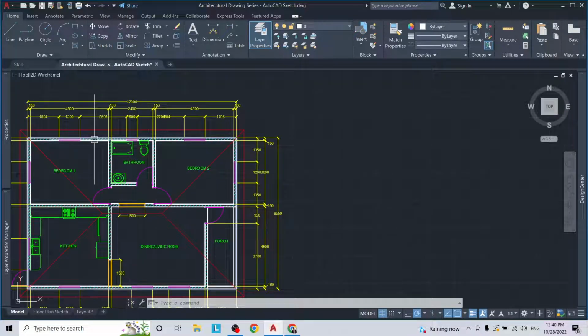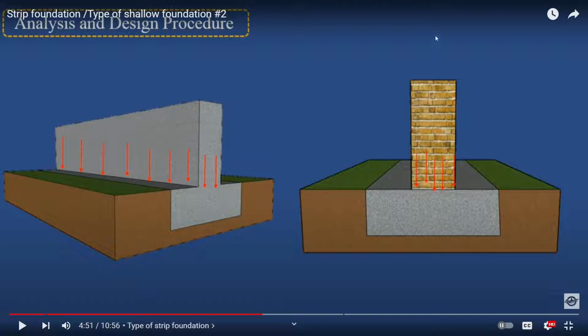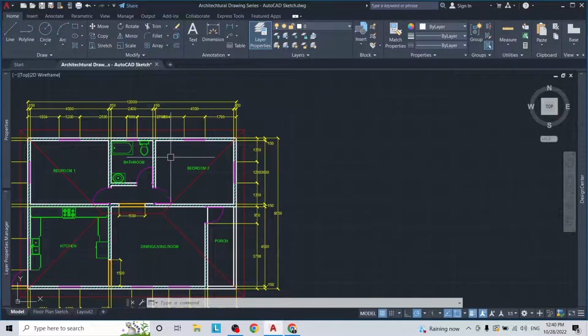Underneath each of these walls, there's going to be what is called our foundation wall, and that's this wall. So underneath the wall of your house, which is going to be above here, you're going to see there's going to be a floor, and then beneath that is going to be the foundation wall. And then underneath that foundation wall, you're going to see what we call a footing, which is a reinforced strip of concrete that runs underneath all of the foundation walls that run underneath all of the walls of the building. So I hope that was clear.